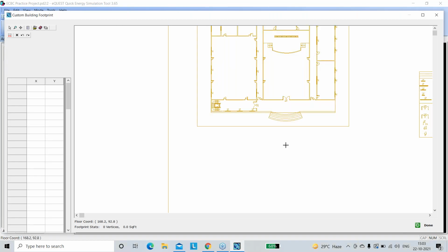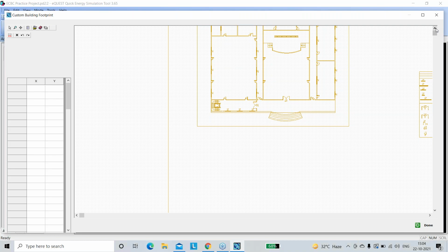So here you can see that the entire CAD geometry is imported. Now, what I would be strict about is I will not import any detailed CAD drawing here, something that has blocks and everything. I would refrain from doing that.